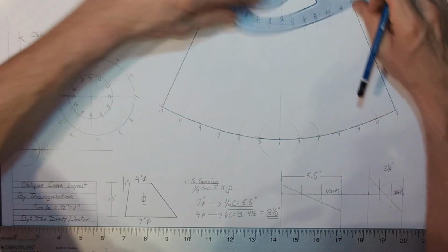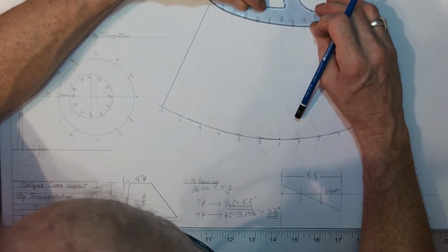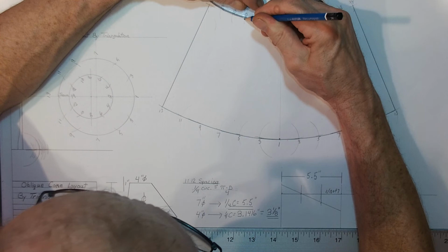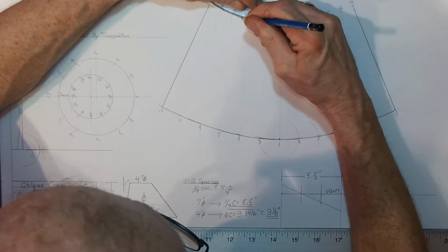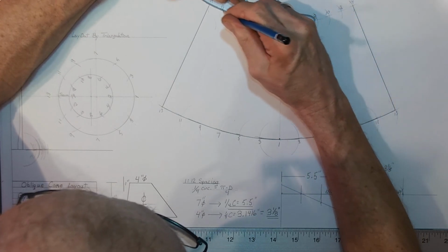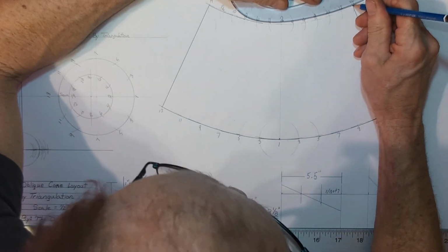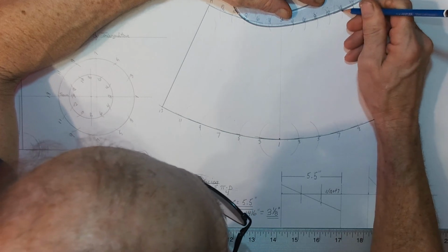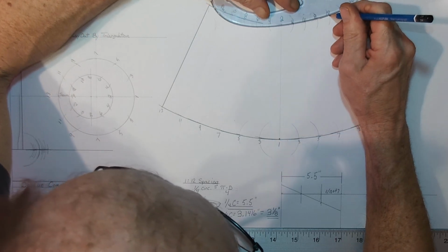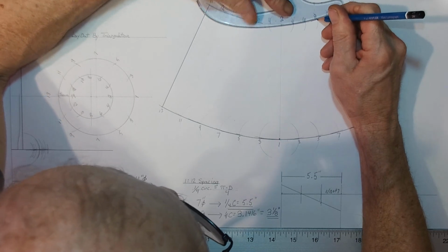Do the same thing. Oh, there goes my keyboard. On the top, I'm going to find a spot on the French curve that will work for a few points, starting with the 8, for example. And I'm just going to go a little bit both ways. Back to the 8, and we'll carry that through to about here, back to here, connect it. Going the other way now. Put my start on that 14. Oh, look at that, I can go past the 12 just a little bit, go to the 12. There's a couple more. I'll come back to there and stop. I'm just past the 8 and stop.